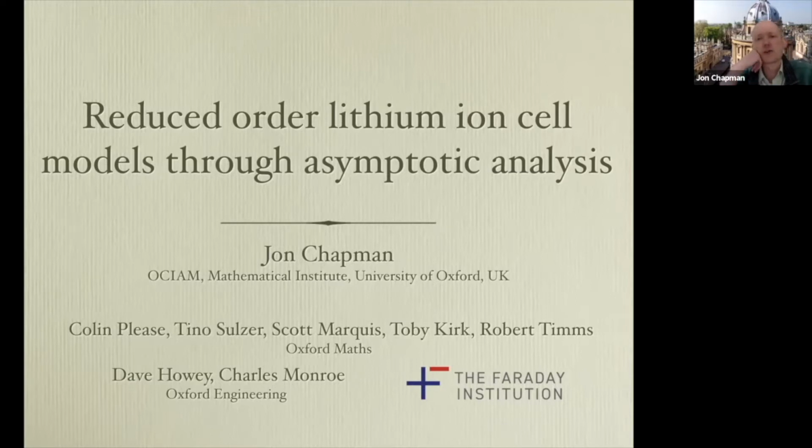And then a question that arose in the question answer session was, could you ever get a physics-based model like DFN into a battery management system given the reduced processing power? So I'm going to try and address both those issues through doing reduced order models, so reducing the complexity of a continuum model through a systematic asymptotic analysis. And I'll try and give you an idea of the advantages of doing it systematically through asymptotic analysis.